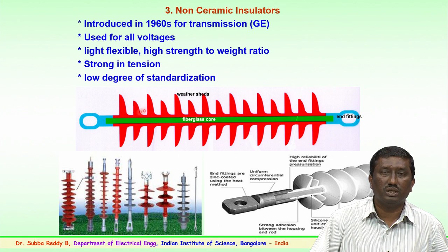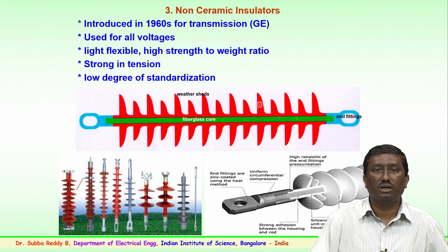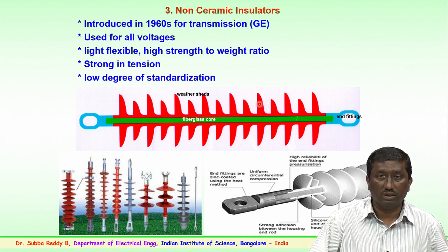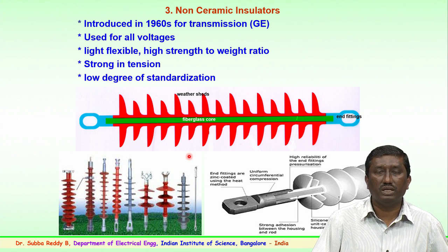and the creepage distance of the insulator required. So, all these factors will dictate for various voltage levels. These are of recent origin, are being used abundantly in the country and also in several other places across the globe, and they have promising characteristics, particularly for pollution performance. They are immediately better performing than the ceramic or porcelain insulators.